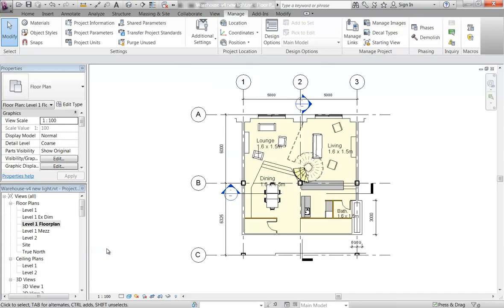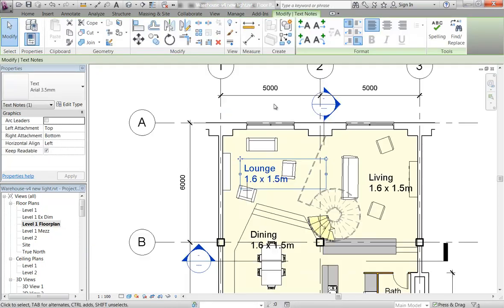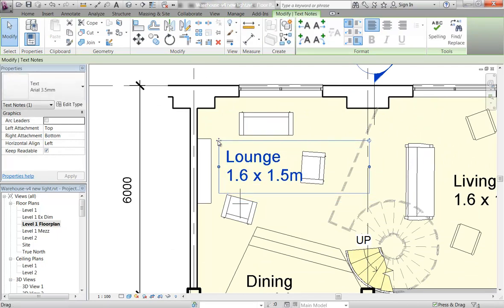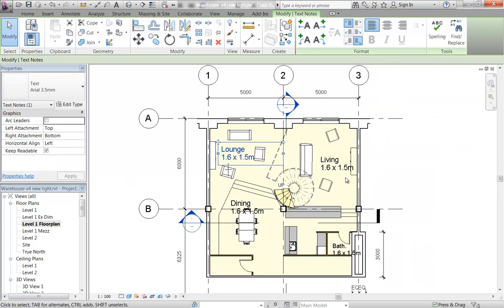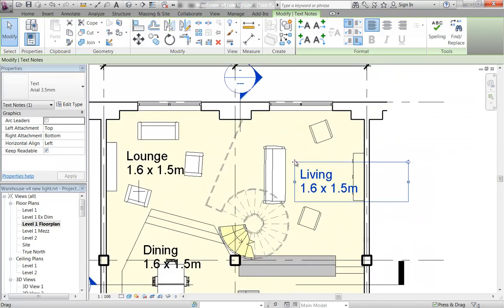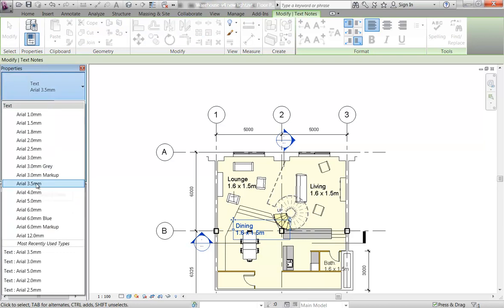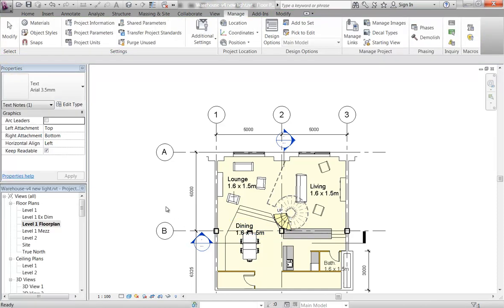So again, it's important that you understand why different scales won't fit at certain sheet sizes. And then when you adjust your scale, things like your text will change size. They should, because in properties you've got the size that it'll print. In properties, this one, in the drop down. So you've got to click on the text button, and then you'll see it in properties.